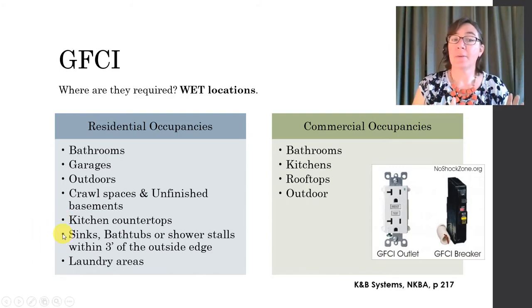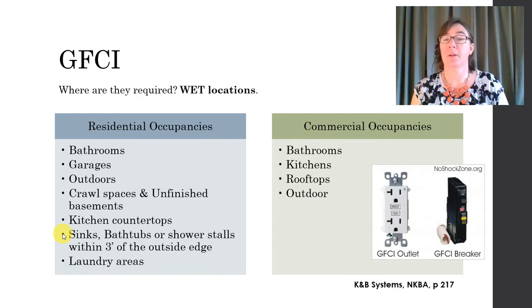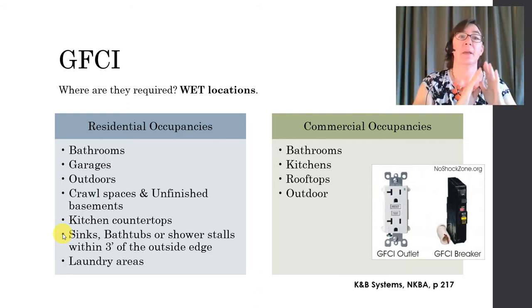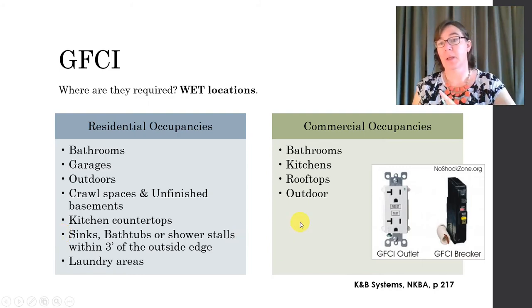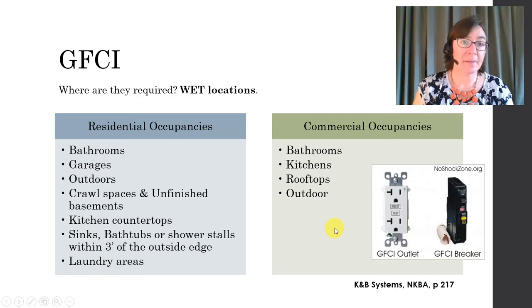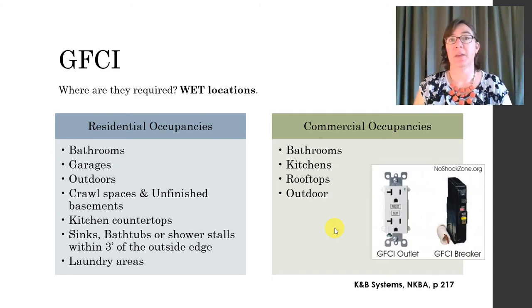Within 3 foot of the outside edge of any sinks, bathrooms, or shower stalls, and in all laundry areas, GFCI is required. Okay. For commercial occupancies, you need them in bathrooms, kitchens, rooftops, outdoor. All right, so just in general, if it's possible to be wet in that location, you need to be GFCI protected. Here's a picture over here of what that outlet might look like and what that breaker might look like.